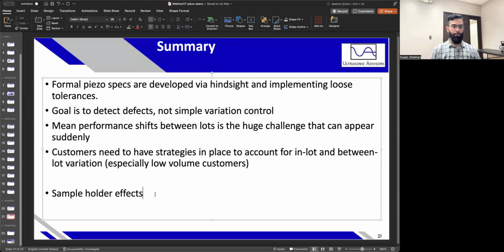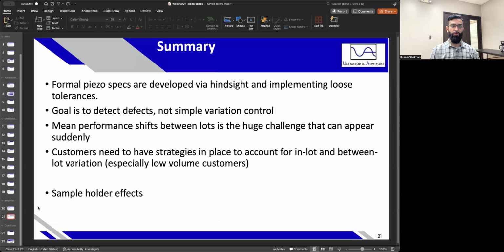it is definitely possible to get through, and having a good data sheet for an appropriate stage of your product is important, so you understand what you need to. It's not only for the supplier, it's also to understand when you receive devices that they may be out of specification, what that does, whether you can indeed expand your range, and to know that you have particular performance differences for a particular reason. Measurement of your ceramic elements is important before assembling your device.